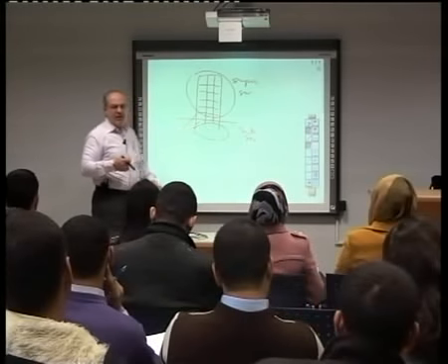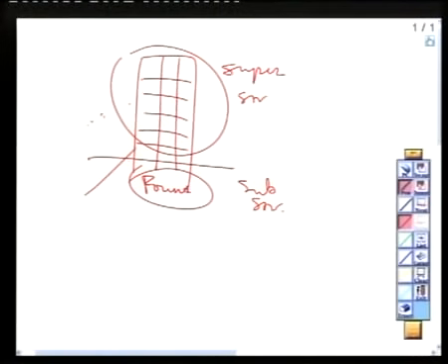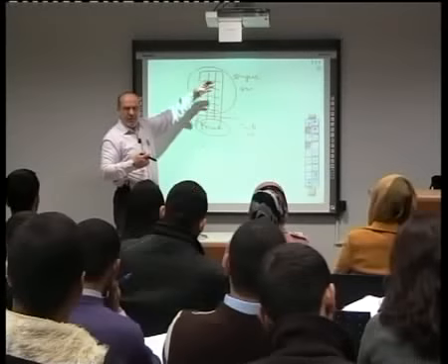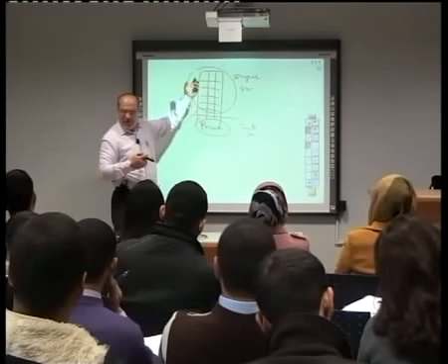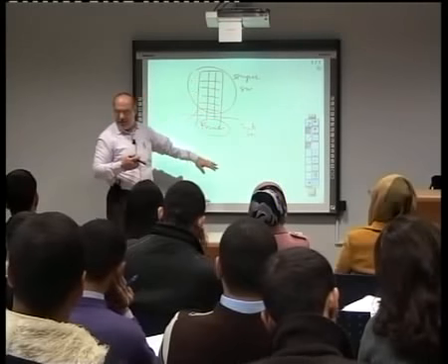The substructure, they are foundations. Foundations, the design of a foundation. Foundation is an intermediate structure, which takes loads from above and sends them below, right? These buildings, all buildings rest on the earth. So the load comes from the walls, from the slabs, from the beams, to the columns, to the foundation, and from the foundation to the earth.